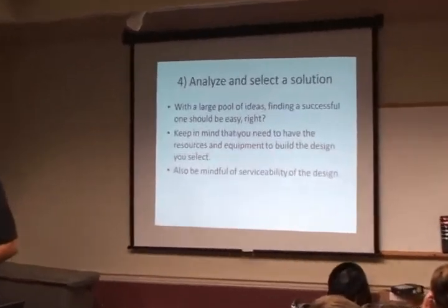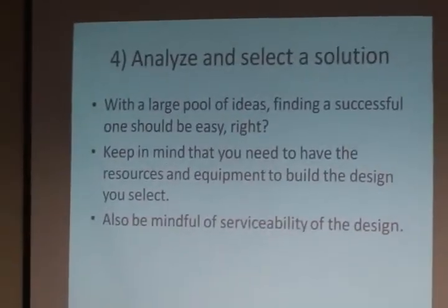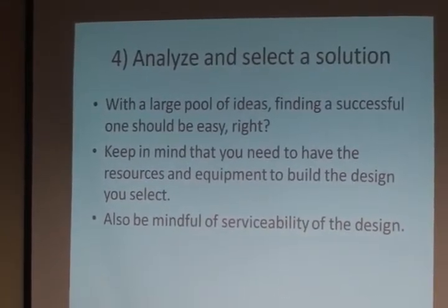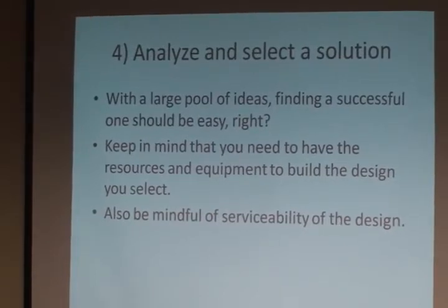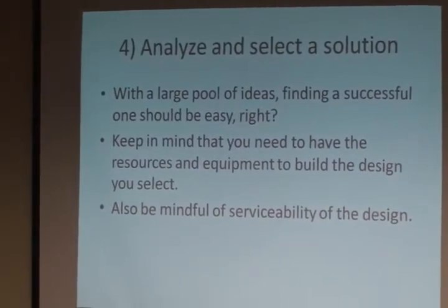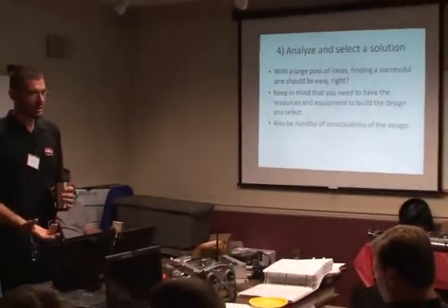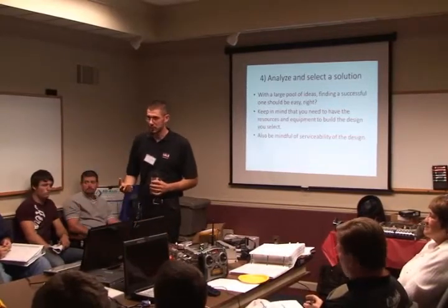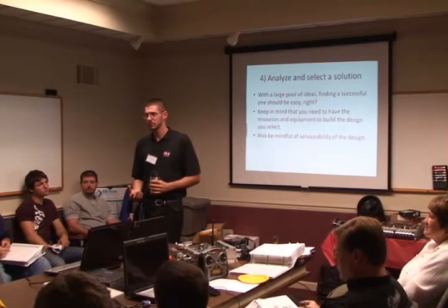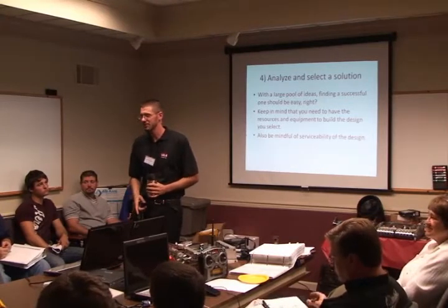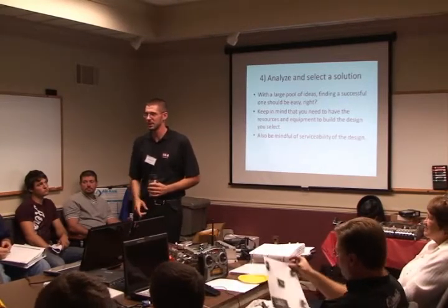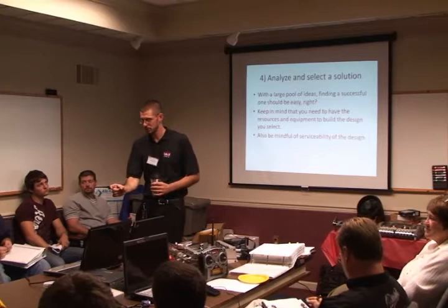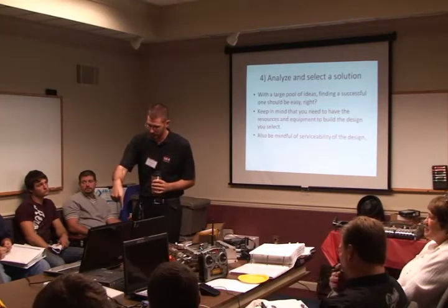Alright, so you selected a solution. Took all those crazy ideas of levitating robots and robots that have cloaking devices so the other team can't see you. Remember, you gotta build it. You can draw anything on a computer, it'll all bolt together on the computer. But when you actually go to build in real life, you might find that you can't actually get a screwdriver on that screw inside the middle of that chassis because there's another chassis rail in the way. Or you might find that you pulled the tolerances so tight you can't get to that screw.